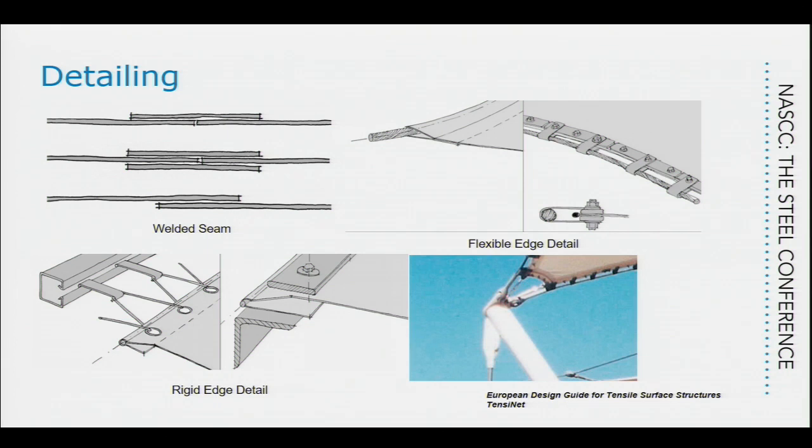So this is some of the interior seams, and I'll show you what those seams look like once it's erected. But sometimes when we try to stretch it in place, we use a cable: you create a pocket, thread a cable through, and pull on that cable to get it in place, stretch it, and generate the stresses we need to create the shape.